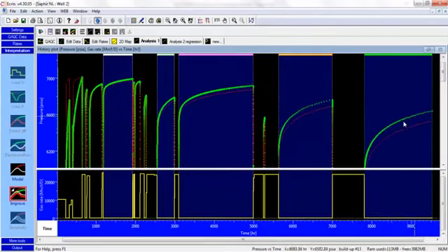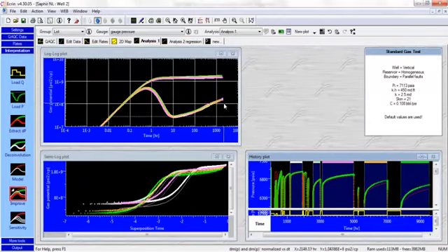So now we are missing something here. And what we are missing is deconvolution. We matched the model only using this conventional derivative, only using this short shut-in duration, but we've got information over 9,000 hours, and we don't use that. We don't use any information here. So we need to investigate deconvolution, and try to recover a reliable deconvolved response.